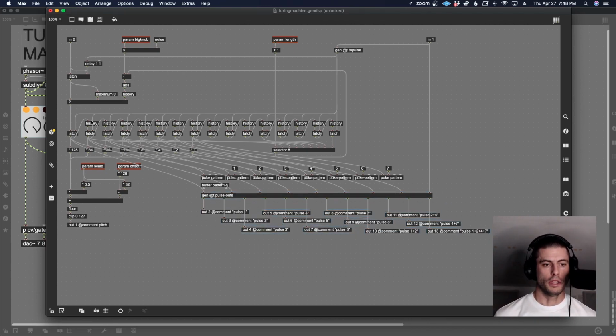And we'll rebuild this, but essentially, this is the shift register section. We'll talk about exactly how that works. Here, we're taking the first 8 stages of that shift register, and we're scaling them by these various values in order to turn the 8 bits into a number. In one of the videos that Tom Whitwell, who developed this device, made, he describes this as a DAC, digital analog converter, which makes a ton of sense, right?